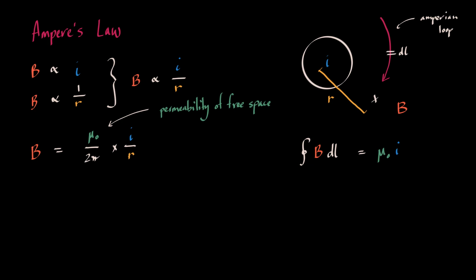While B denotes the magnetic flux density, the strength of the magnetic field is termed H. The distinction between these two lies in the complications that arise when generated magnetic fields pass through magnetic materials, which themselves contribute internal magnetic fields. H unambiguously designates the driving magnetic influence from external currents in a material, independent of the material's magnetic response.